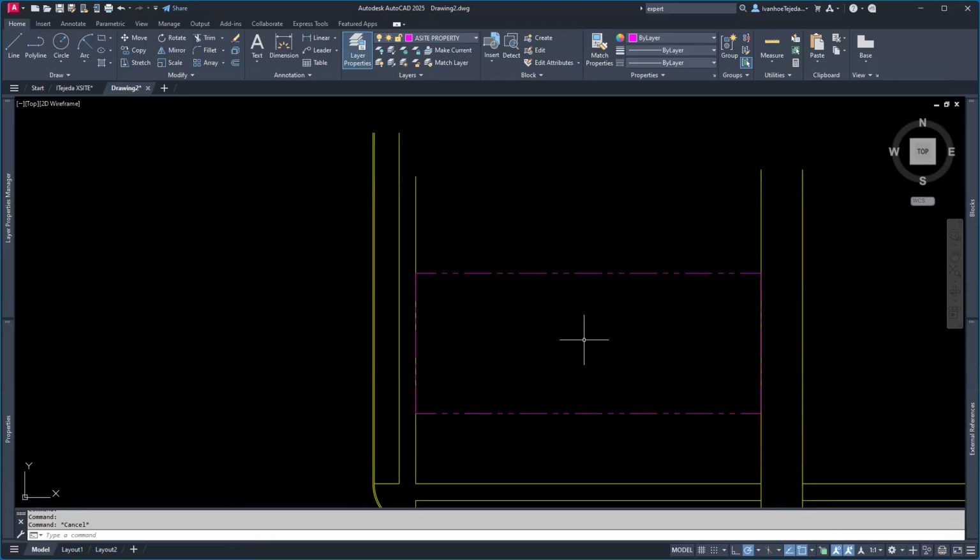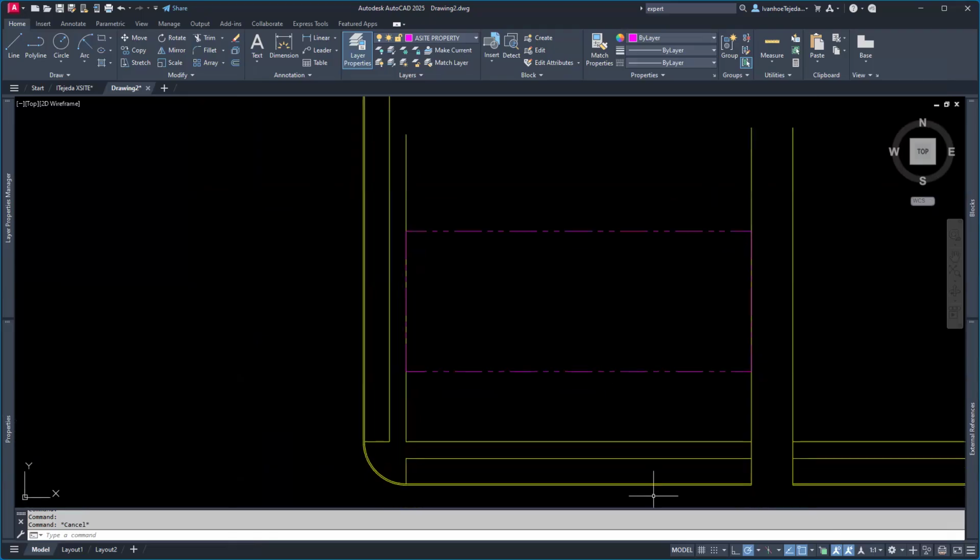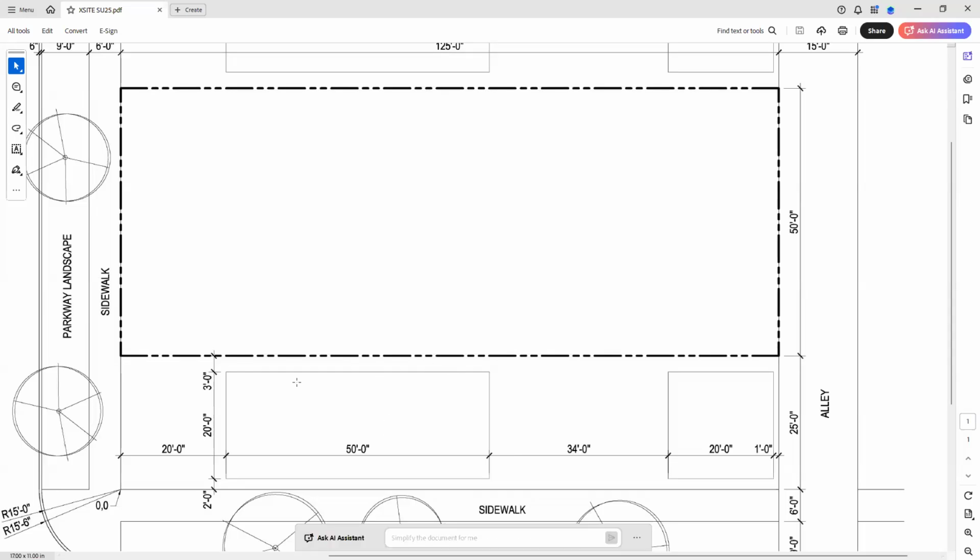Next up, the buildings. So if I go back to my example, didn't mean to take it away. I just want to put in the buildings here. And a typical city lot is 25 by 125 and you have a building on there, it's usually 20 feet wide because you need setbacks on the two sides. And it's either 2 feet or 3 feet or 2.5 and 2.5. Either way, it adds up to five.